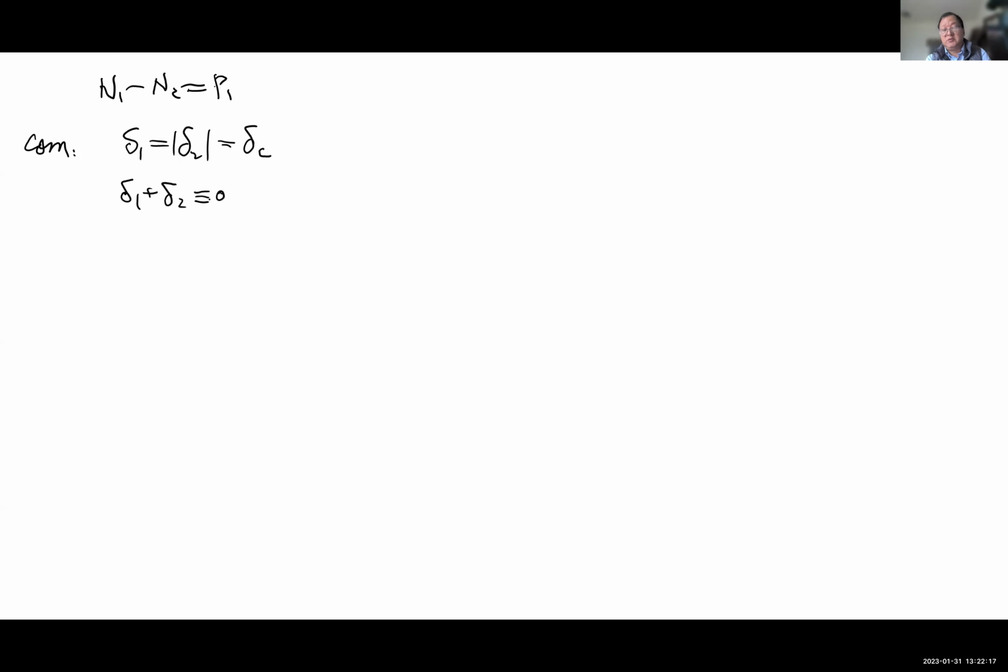This is basically the same thing. It just depends on which view you're thinking about the geometry relation. You can think this way or you can think this way. Either one gives you the equation. So now let's translate this into an expression so we can solve this problem. On that first equation of compatibility, is that elongation 1 equals the absolute value of elongation 2? Yeah, so basically you can write it this way.